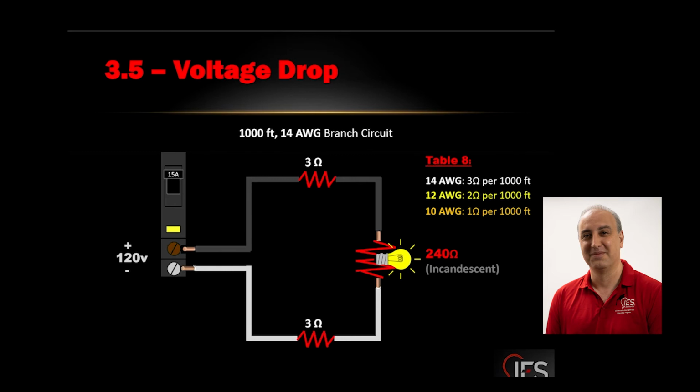I'm not sure if they teach you the formula in this one or next pod, but George will give you examples of voltage drop calculations. You did that already? Okay. So if you do your calculations, you see that the voltage that that light bulb will see instead of 120 is 117. So about 3 volts has dropped from here to here because of the wires.